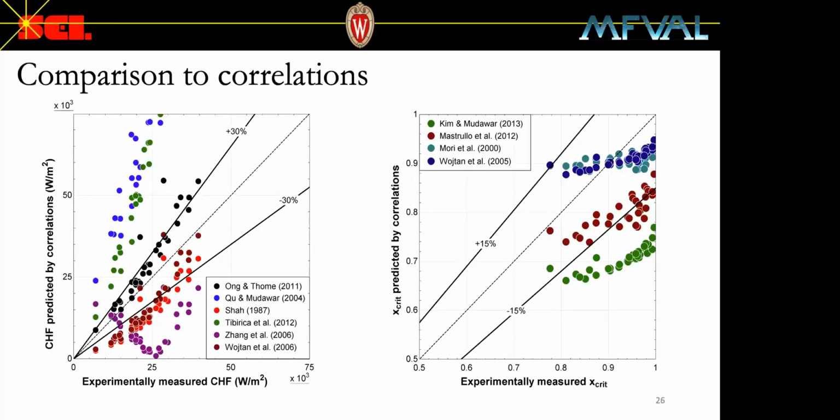For critical vapor quality, the correlations that provide the closest estimate, so here, fail to reflect the trend of the data. However, the correlations that best reflect the data trend, here and here, fail to accurately estimate the absolute value of the experimental critical vapor quality. The lack of good agreement between the different correlations in the literature demonstrates the need for a more detailed description of the boiling crisis phenomena based on local time-resolved measurements.